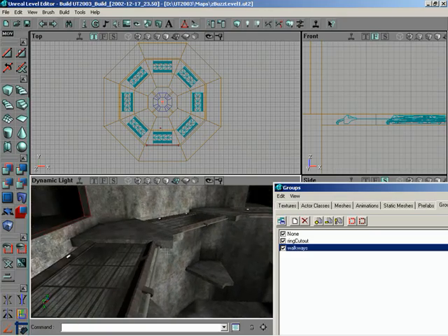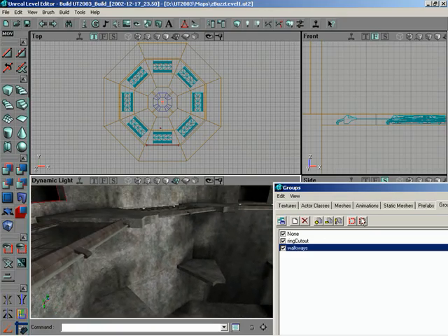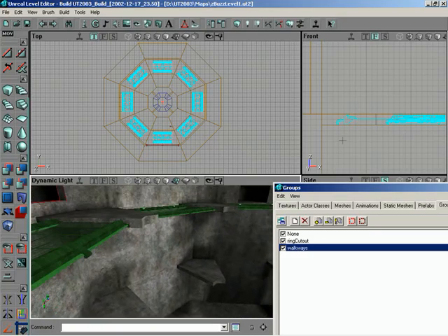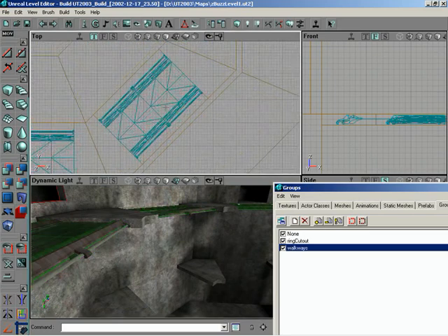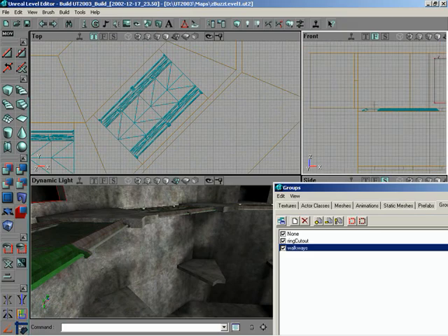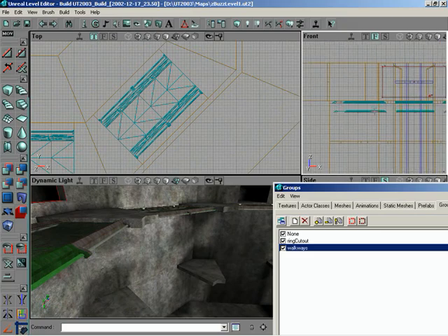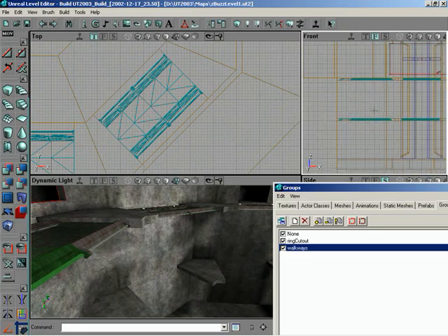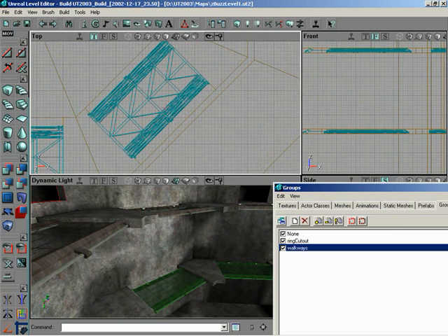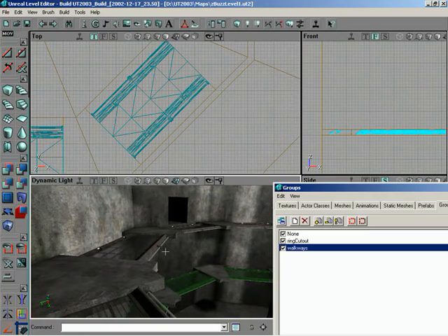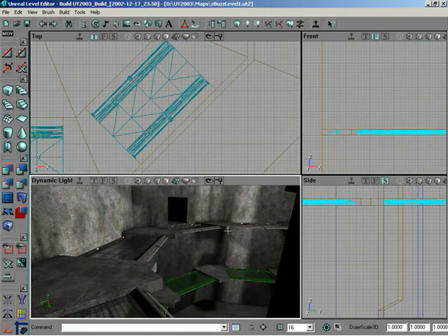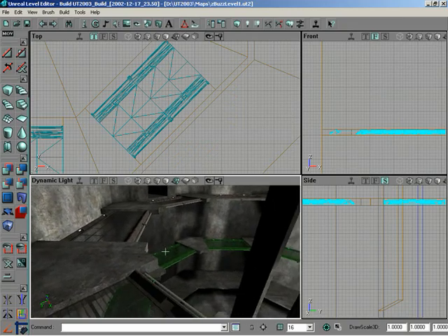So now we need those same 8 on that lower ring, so we can go back to our group browser one last time, select all 8, Control W to duplicate, and make sure that they center up again. And then from front view, I'll just Control drag them straight down. And if they line up, yeah, I moved them a little, so center them. Centered, centered. And there we have walkways for both levels. Very nice. I'll go ahead and close out the Groups browser. Okay, so that takes care of our inner circular walkways.